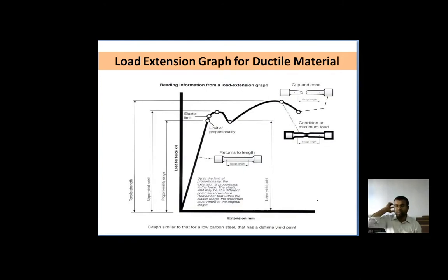The load elongation curve from a tensile test and the corresponding engineering strain curve, for a specimen with a diameter of 12.5 mm and a gauge length of 50 mm, are included. So these figures are from real life practical examples, and that is the standard based practical example figure. That is how the stress strain and ductility of that particular material is identified. So this is the basic base of the graph which is drawn in that particular shape.